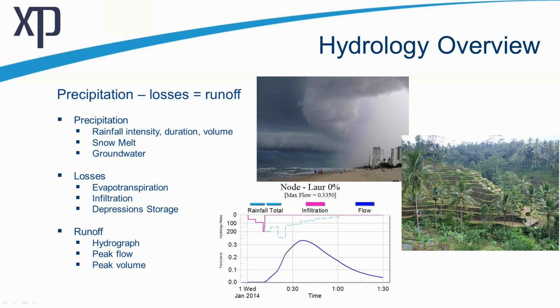We've had precipitation, that variation between those flash flooding type characteristics, monsoonal rain patterns, broad area flooding. We have the losses, the evapotranspiration, storage, infiltration, and then of course you take those away from each other and we can derive our runoff.